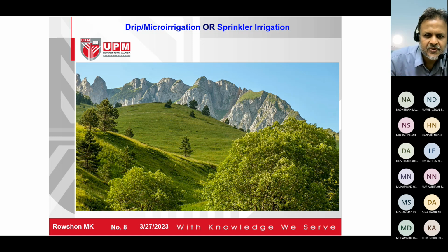Water will be applied by drop. So when you apply water by drop, this water will not move like this. There is no runoff. The soil will hold it. You see, last time I told you about holding capacity. What is the holding capacity? Field capacity to PWP, or maybe field capacity to your MAD. Because we don't supply water after field capacity. We supply water until field capacity.